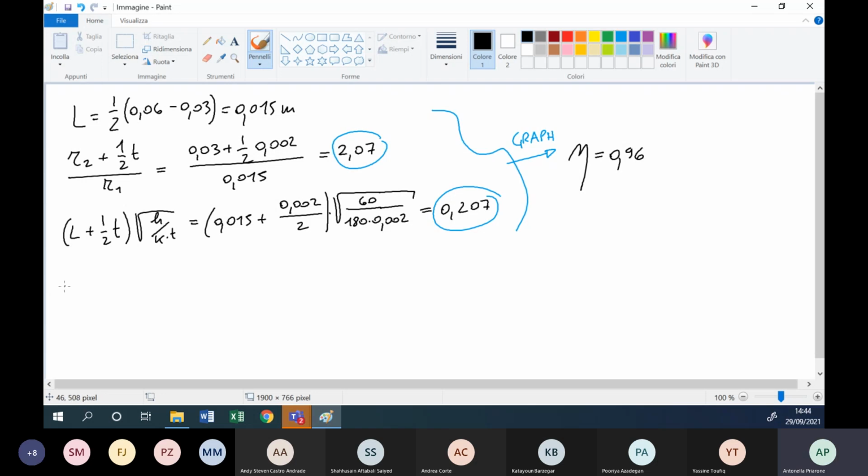Then I calculate for my case the area of the fin, that is equal to 2 pi times 0.03 squared minus 0.015 squared, plus 2 pi by 0.03 that multiplies 0.002, and I obtain 0.00462 square meter.